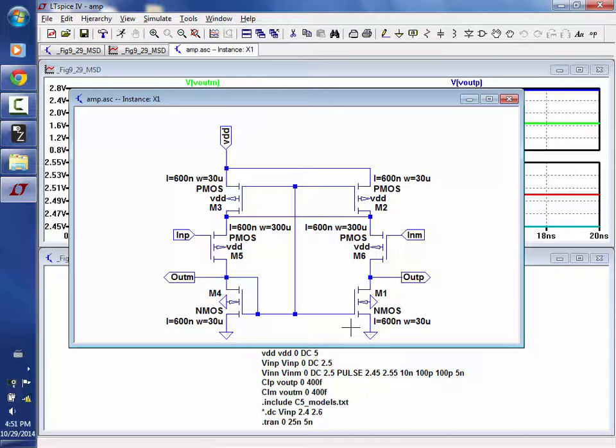So comparator inputs are two NMOS devices. This amplifier's outputs common mode signals, the VGS, so they meet together and meet well, all right? It's not like these swing around VDD over 2 and the comparator inputs swing around VDD over 4. They're both going gate drain connect, or gate source voltage out to the next gate source voltage. So I'm not going to drive anything real deep into triode and kill the gain, all right?